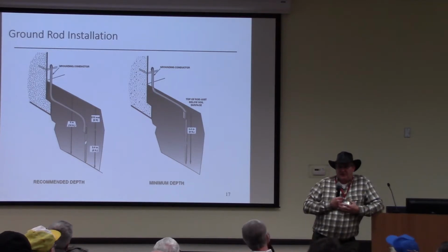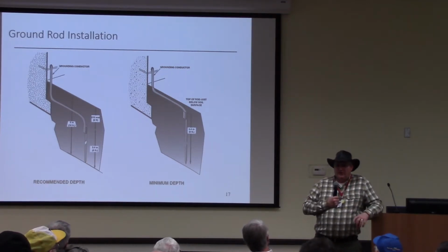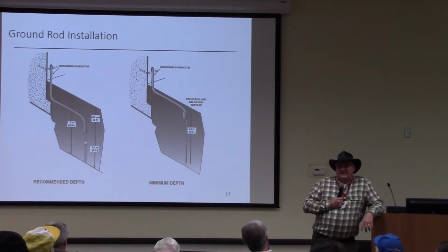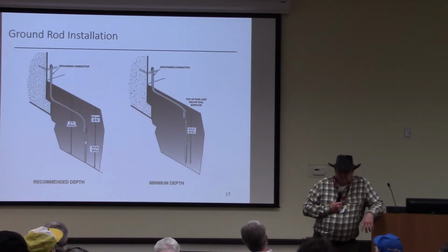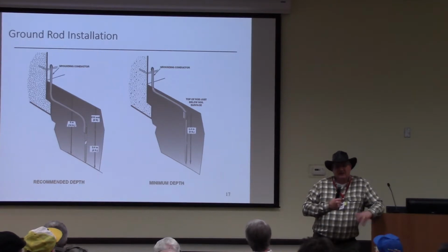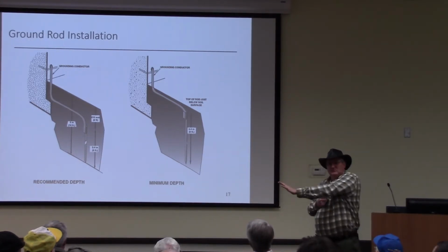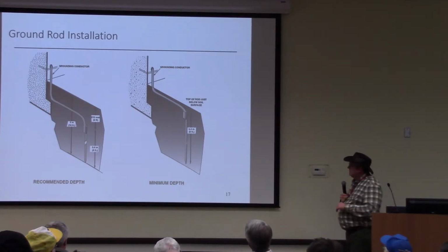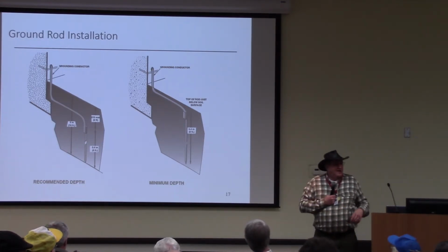You still get the same potential. It'll build up to where that breakdown point is, and then it'll discharge through there. Ideally, that being the path instead of where. Exactly. The idea is directing the currents away from anything going inside. So that's how arc gap protection works. Is it destroyed when that happens?